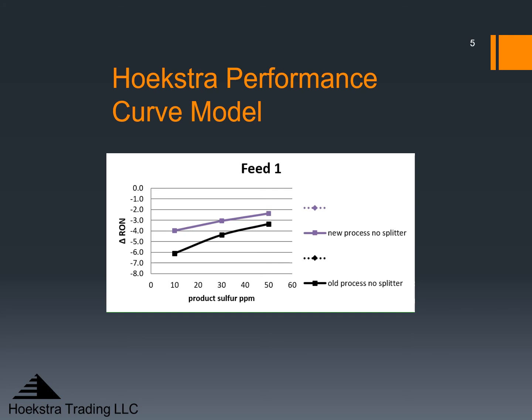Some additional reactions add to octane loss near the end of the cycle and move the curve down, as I have shown here. And secondly, reducing the endpoint of the gasoline will tend to move the curve upward, and I am showing that effect here.